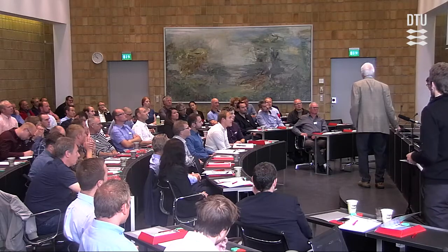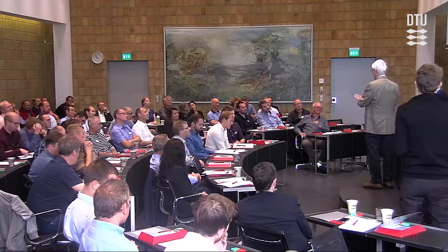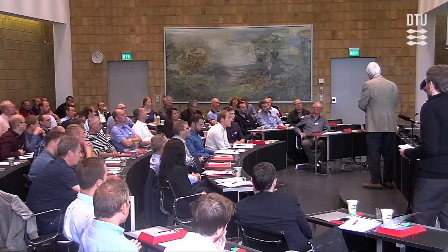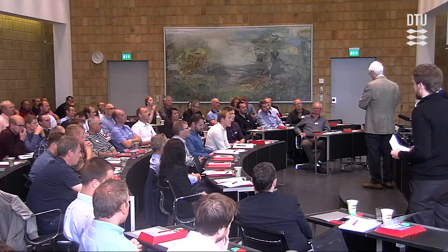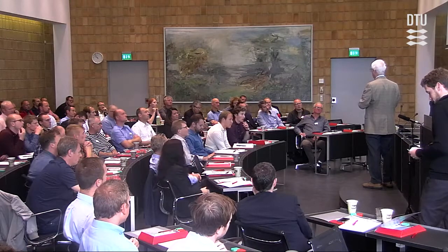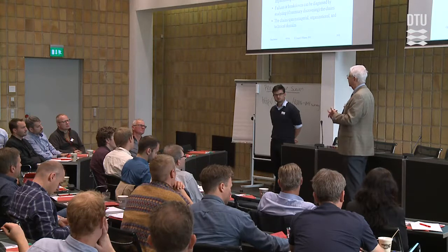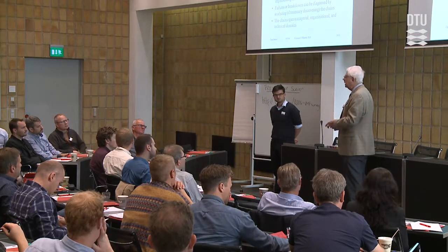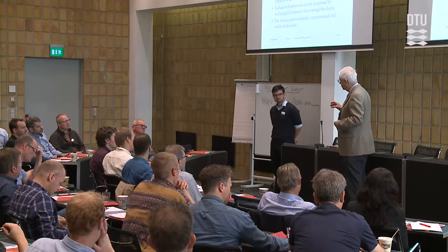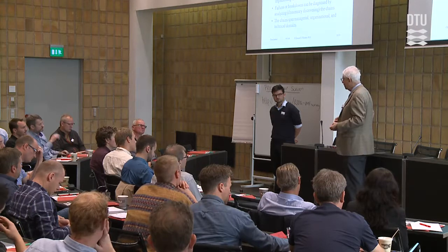Well, it gets crazy. First of all, you have to see if they all deserve to be key characteristics. This is one of the points that Anna Thornton made a few years ago. A key characteristic is something that's important for one reason or another, for function, for regulatory, for safety. That's number one. And number two, that it's at risk due to variation because of variation in manufacturing or assembly.